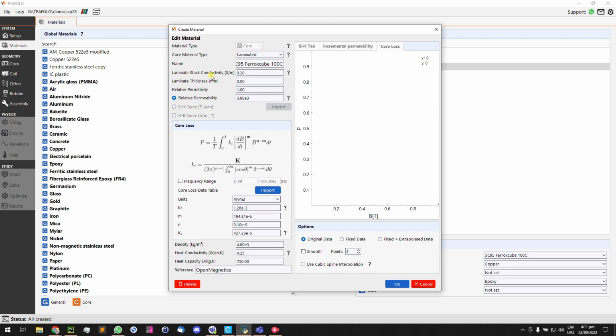And speaking about some other methods, there's actually another method that is being used in the software. It's called the laminate stack model, that allows you to treat the effects of eddy currents introduced in electrical steels, and this, let's say, phase shift, I guess. Well, I'm not very detailed into this topic, but basically what you can do is to account for laminations in your electrical steel cores.